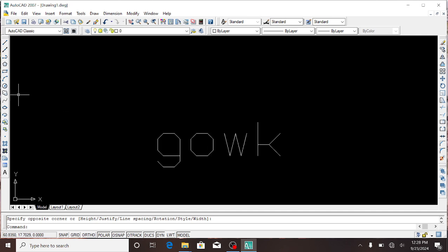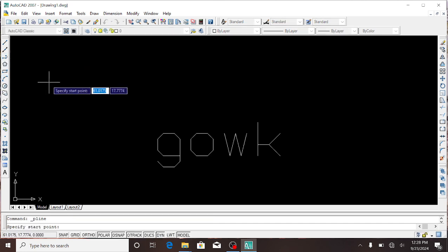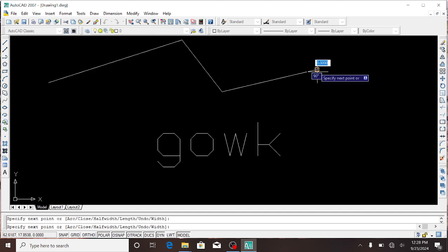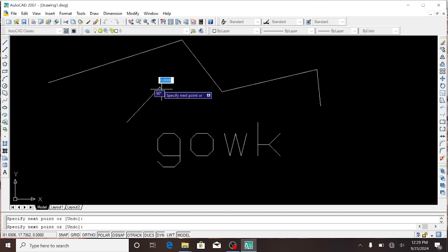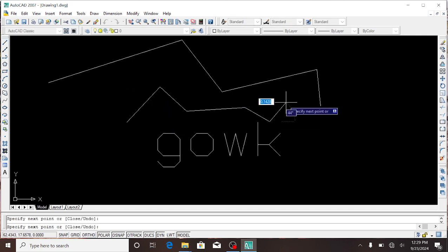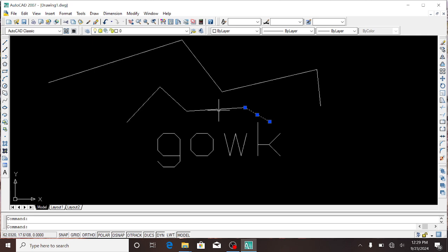So spiral is if you want to draw the arc of a circle. You want to draw the polyline. These are lines whereby once you select it, select it all, they are all connected. But if you pick line like this, where you draw and you click, it will be different lines. But the polyline is as if they are all connected. So that's how you can differentiate the polyline and the line.